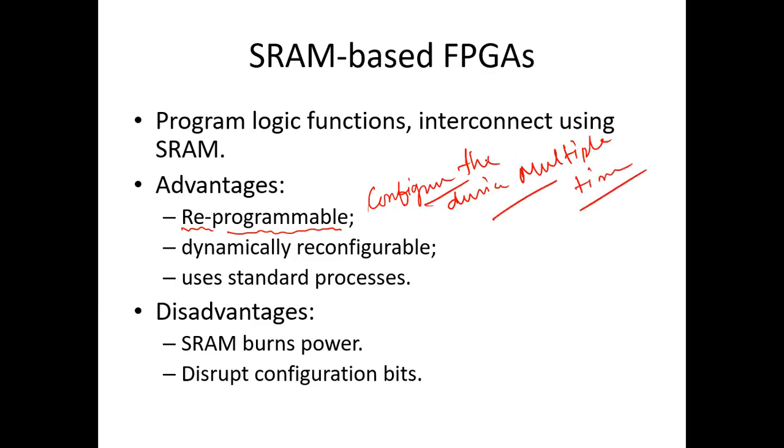That is the reason we prefer this SRAM based FPGA for research purposes. Is that clear? Nowadays we are mainly concentrated on devices which require less power, so this is the major disadvantage in this case. But the interesting part is that you can configure multiple times. That's why we prefer this SRAM based FPGA.